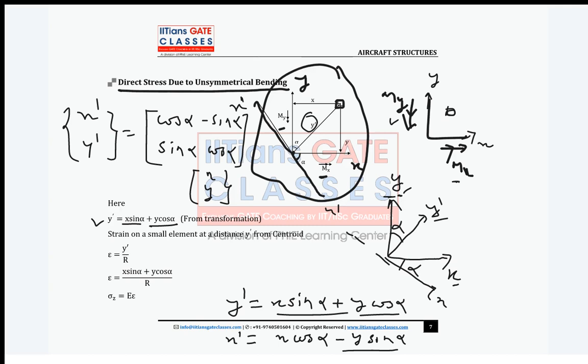Now guys, we need the y dash distance. Why do we need the y dash distance? This is the distance from the neutral axis to the element where we are finding the bending stress.